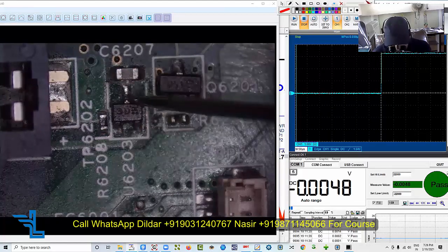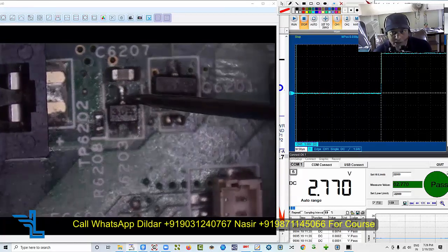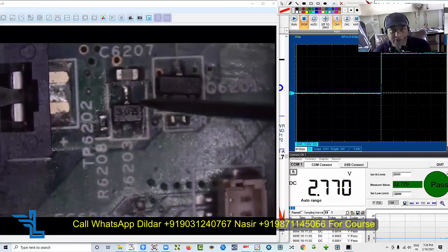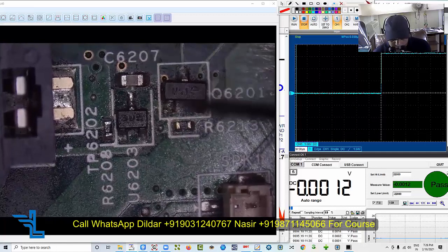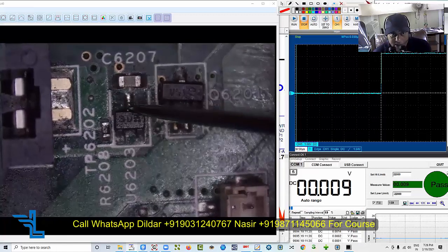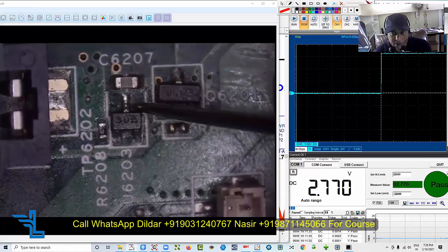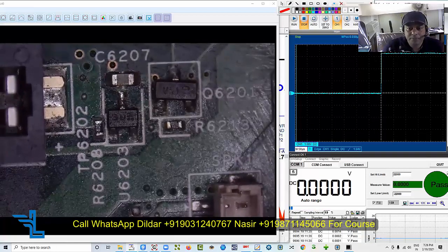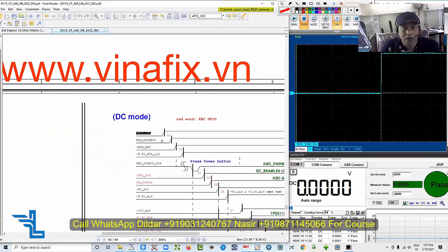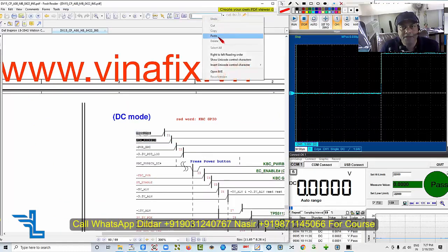That's what it has. It has 2.7 volt. So after reducing the diode threshold value, you will get around 2.7 volt, and you are having it. Okay, 2.7 volt. So it's absolutely fine. Now what else is remaining? Let's go back. RTC reset. Now copy it, paste it.